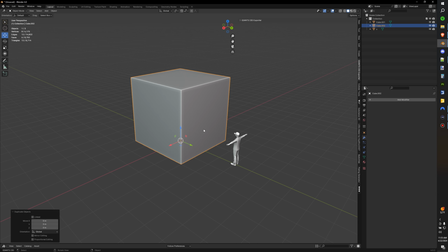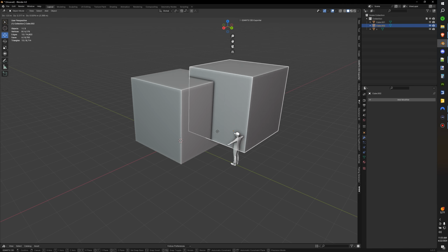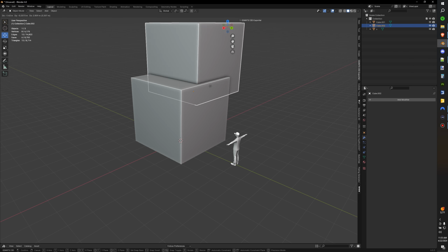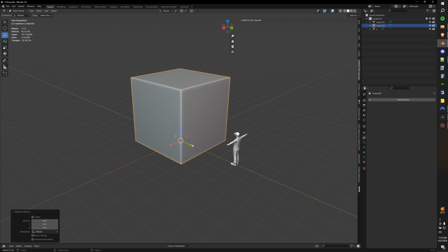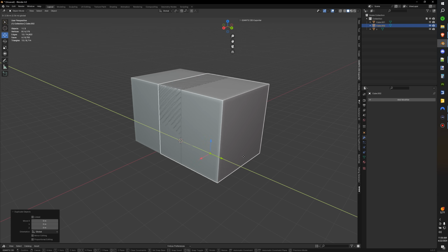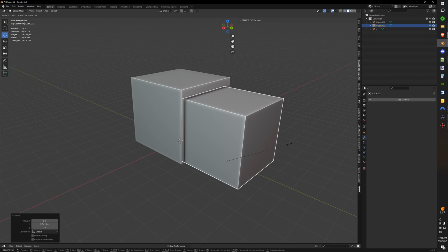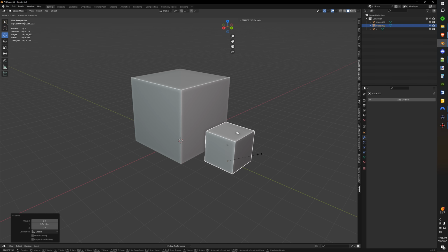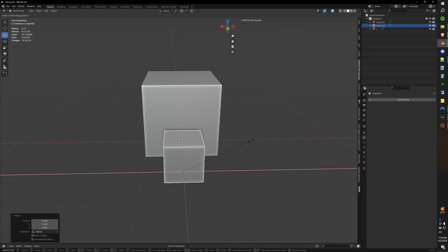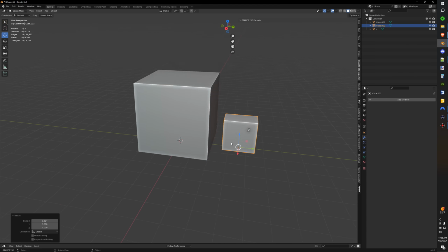So now that we have this cube up, we are actually going to duplicate it by holding Shift and D. So you select the object, Shift and D, and it'll give you this sort of drag feature, right? So Shift D, and you'll be able to do this with it. Don't do anything, just right click. Okay, now that we right click, the box is still there. So we can grab it and move it, and we are going to scale it down to about the size of him, roughly. And a doorway, we could snap out a little bit of his arms there.